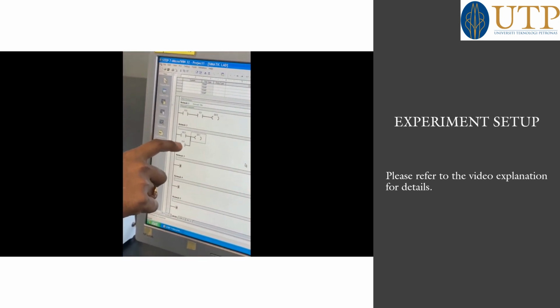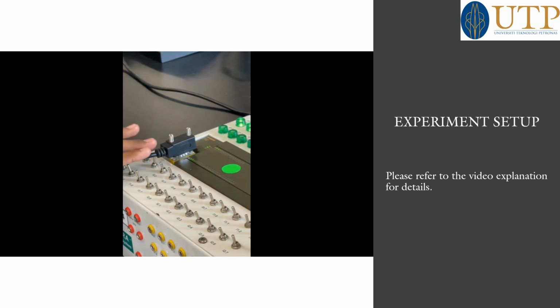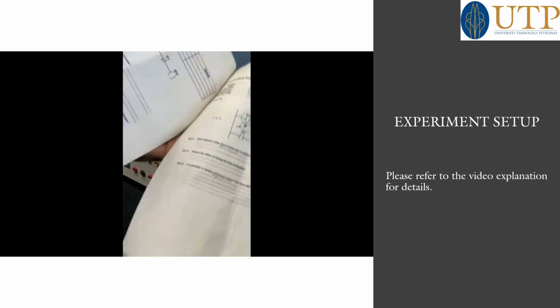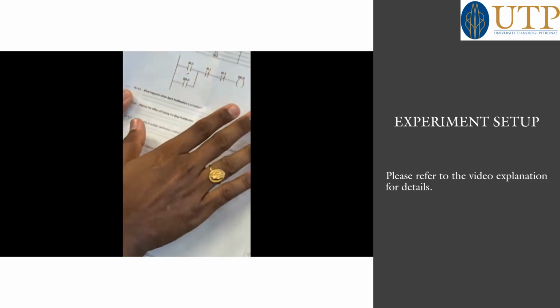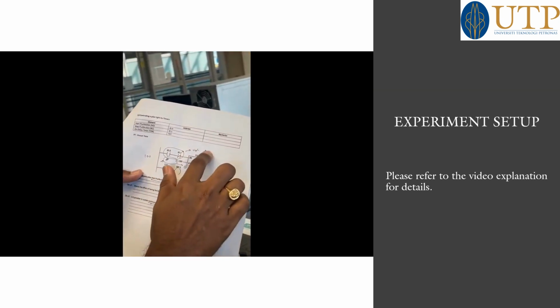So now to get Q0.1 activated, either you need to turn Q0.0 or I0.4. That means either I0.4 or I0.0 and 0.1. Okay, either of the switches should activate Q0.1. So that is the condition. And if you check the second case, it is also same. You need to just replicate and write down your observations.